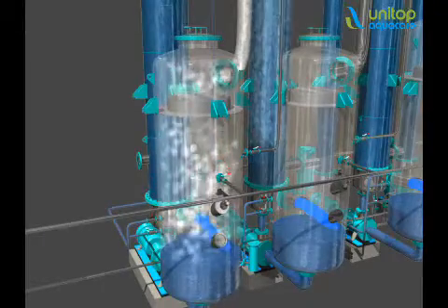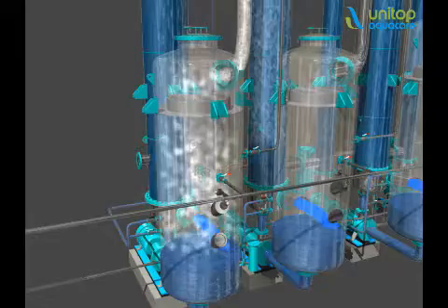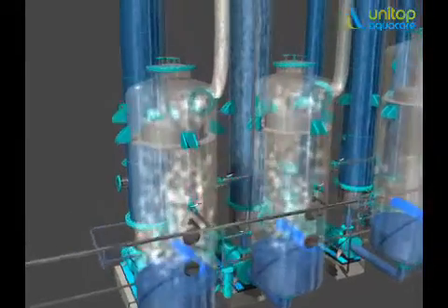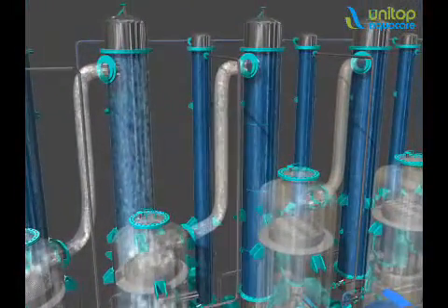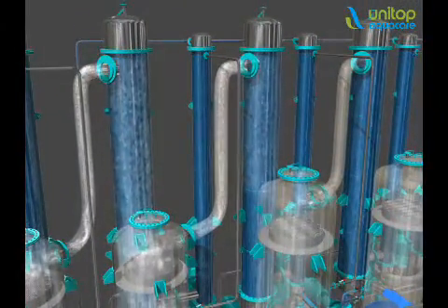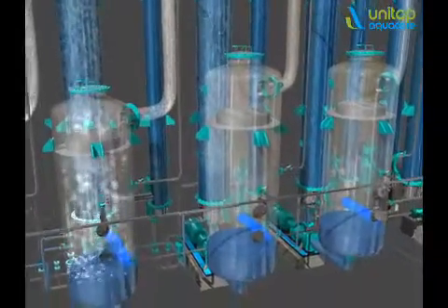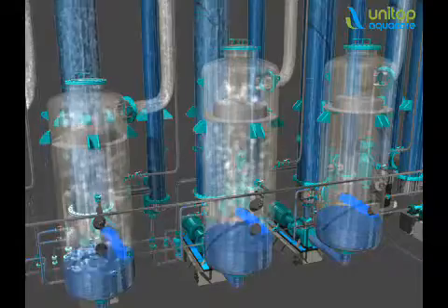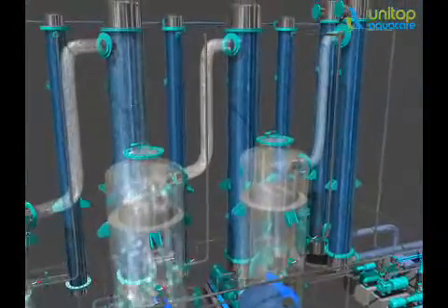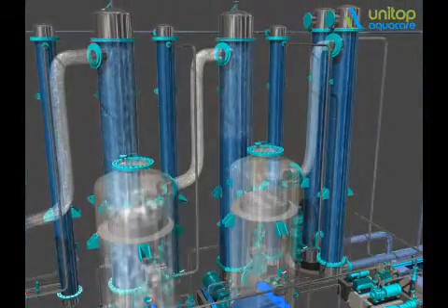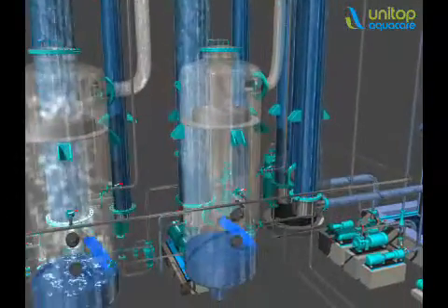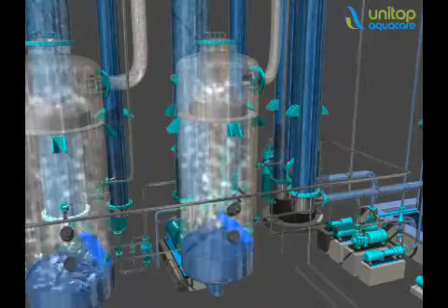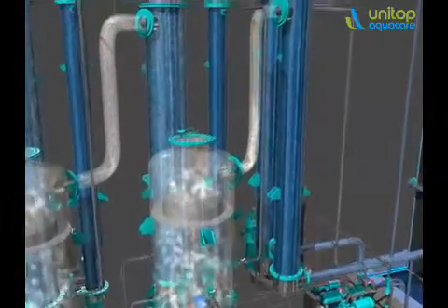In the first flash vessel, some water from the RO reject gets flashed and is converted into vapors. These vapors are carried into the next heater's shell side as a heating medium by vacuum, and again the RO reject passes through the tubes, and thus there is heat transfer between shell side vapors and tube side liquid. Subsequently, vapors are separated in a flash vessel, and the whole process is repeated in successive stages.